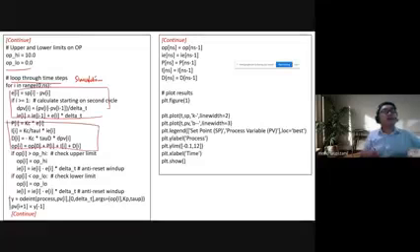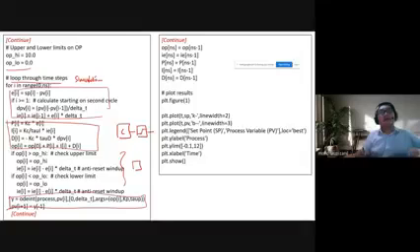Okay, and then the last one. This is the controller, and then you have a saturator, so that the minimum is 0 and the maximum is 10, so that your system will not go above 10 or below 0.